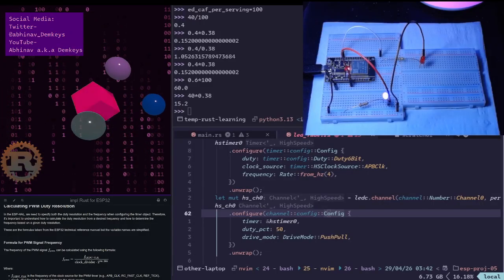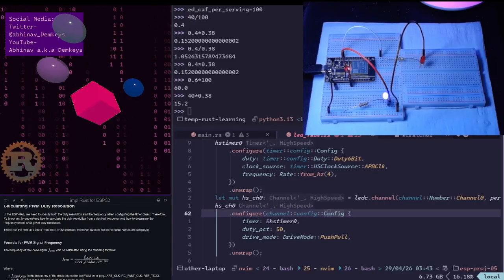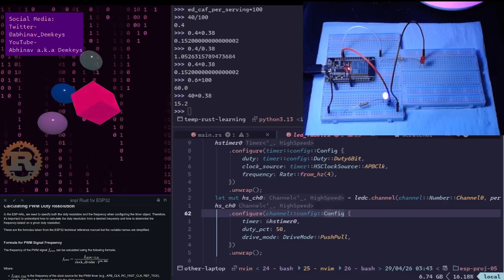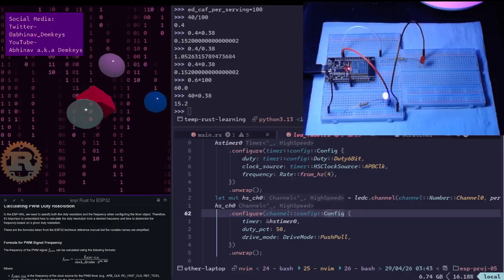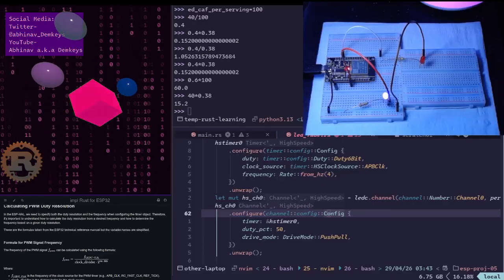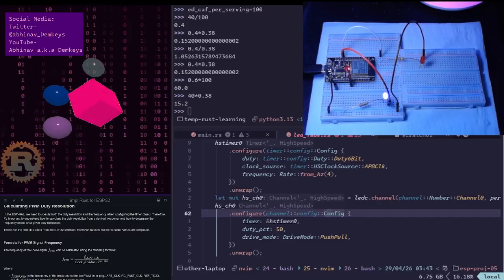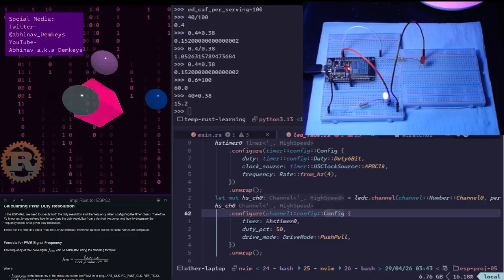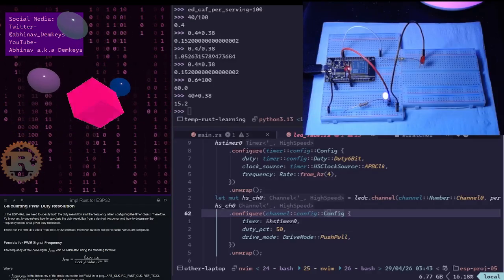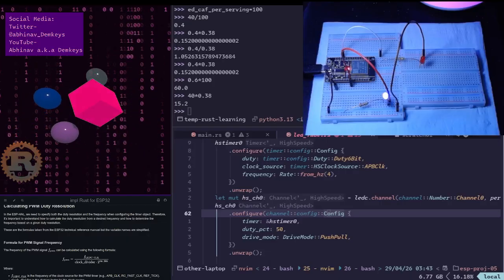The first thing I realized was the main issue I was having was that because of the resolution that I'd set, setting a very low frequency was causing an issue, because there's two places where we can run into problems. One is setting the duty resolution. That's the number of ticks that one period should contain. And so that's one place where you can have an issue.